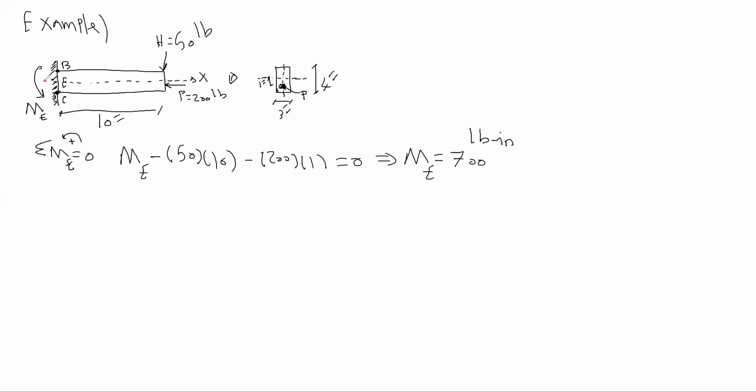We have the force here, and now we want to find the stress at points B and C. In this section, we have two things: axial force P and the moment M. Look at this force P. This is equilibrium. This P in this direction and that P in this direction are the same, so it should be canceled out. So P is compression. It's compression on BC, right?